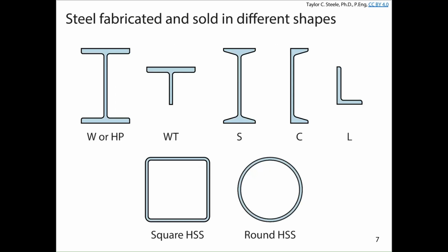We also have different kinds of structural shapes. I'm sure everyone has seen this before. You've probably called this an I-beam in the past. We don't call them I-beams as structural engineers. If someone says I-beam, right away they're not a structural engineer. We call them wide-flange shapes, or sometimes H-piles. Geotechnical engineers will usually call them H-piles because if they're shorter and wider, they use them as piles. If they're wider and deeper, we tend to use them as beams or wide-flange sections.